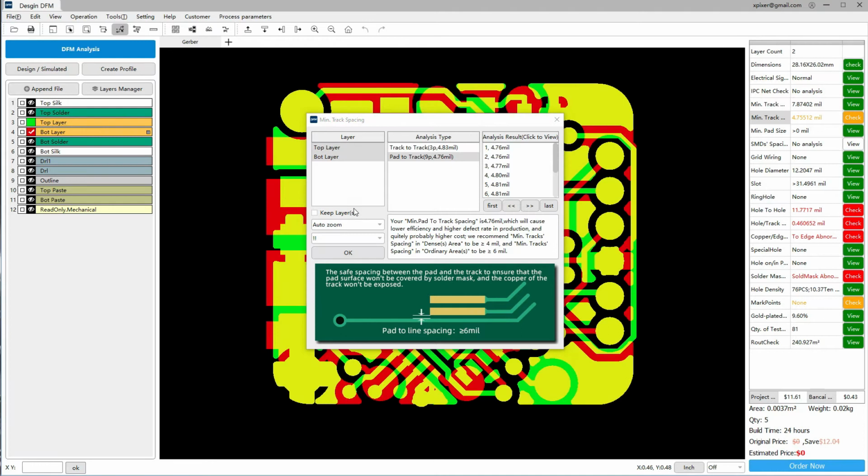In the window, we can decide on the left side which layer we want to see. So in my case, the top or bottom layer. Below, we can decide if we always want to see all layers or only the faulty one. The message consists of warnings or errors, here marked with 1 or 2 exclamation marks. Pan only recommended, so that the error is not unnaturally enlarged and you still know where you are.